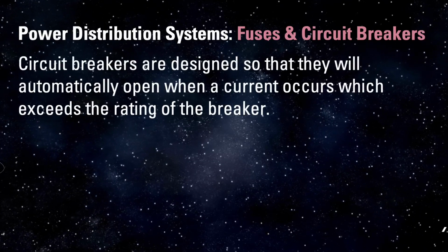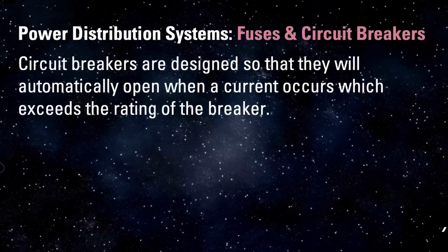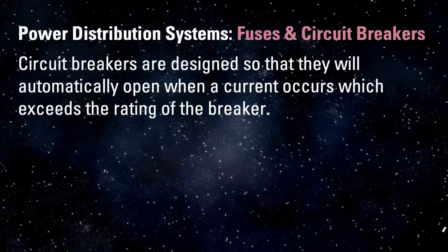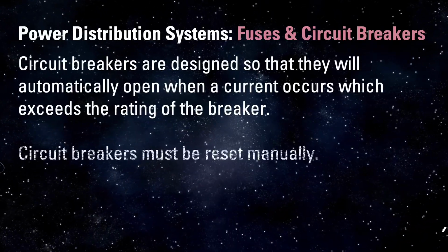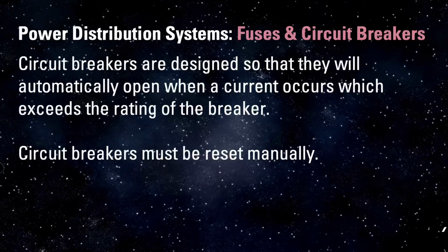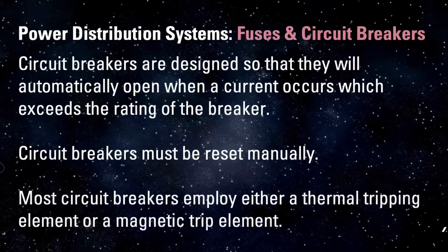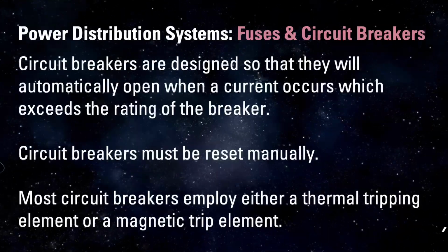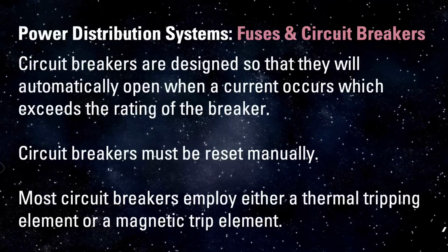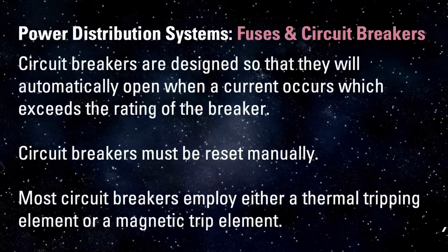Circuit breakers are designed so that they will automatically open when a current occurs which exceeds the rating of the breaker. Circuit breakers must be reset manually. Most circuit breakers employ either a thermal tripping element or a magnetic trip element.